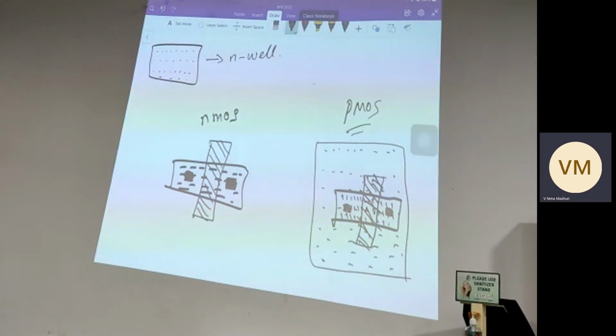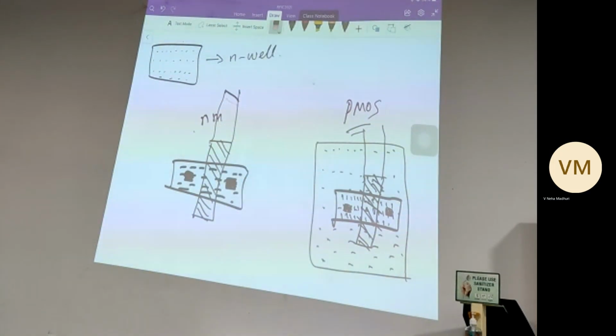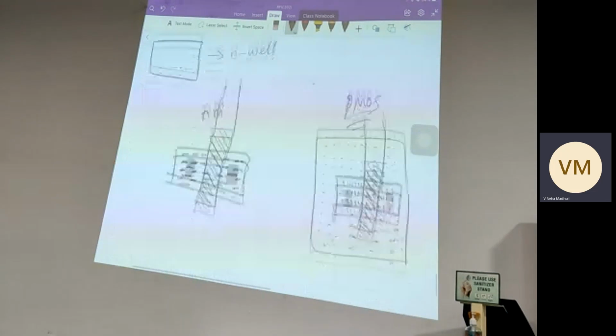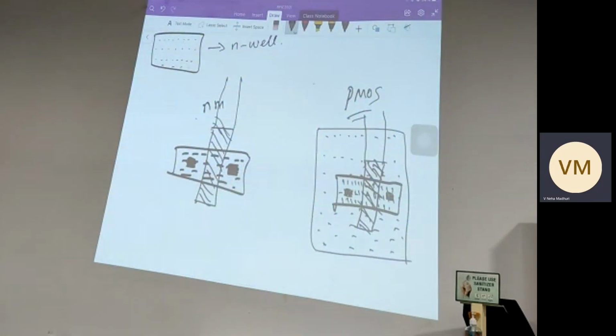One way to make an inverter is I need to pull this and pull this. Not this direction, right? Left slant is what? Yeah, poly. So I pulled a poly and pulled a poly here also. Then I will run a metal line here.